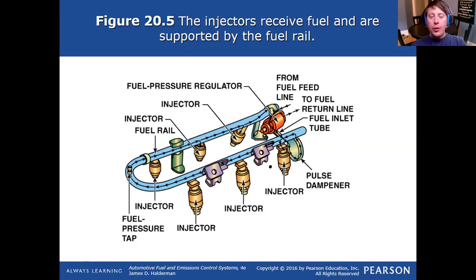So your pulse width modulated pumps on your later vehicles, it's even more of a problem. But on your earlier stuff, if it had an electric fuel pump or a mechanical fuel pump, didn't matter. Both of these styles, they don't operate just on, they operate on and off so quickly that they seem to just be on, but they're actually pulsing fuel in waves.